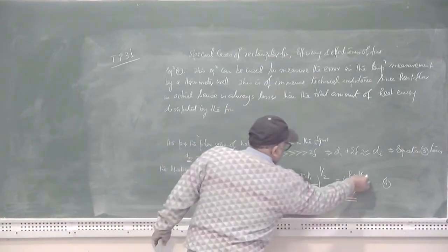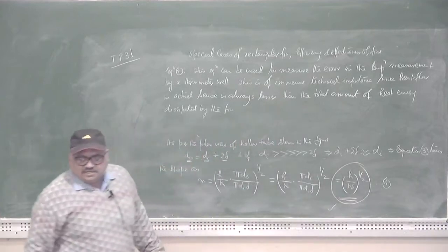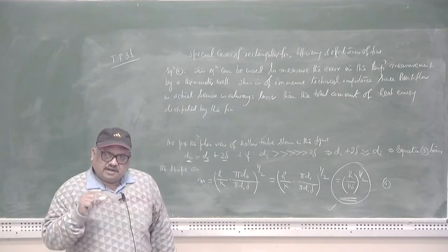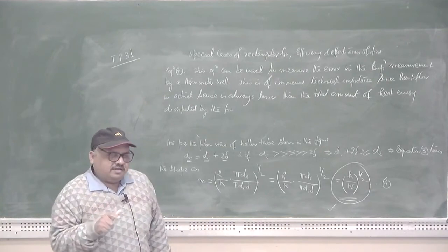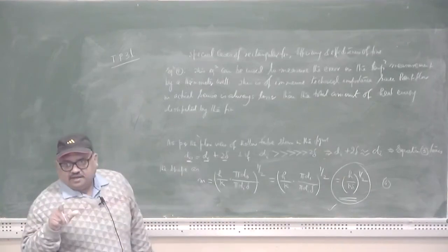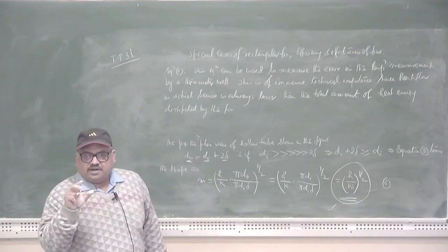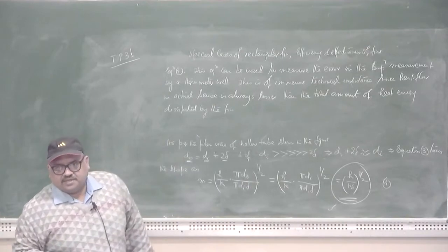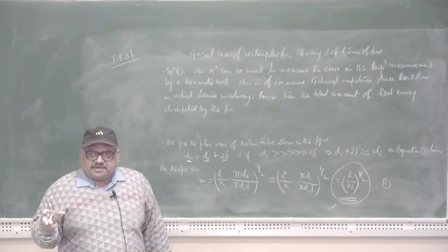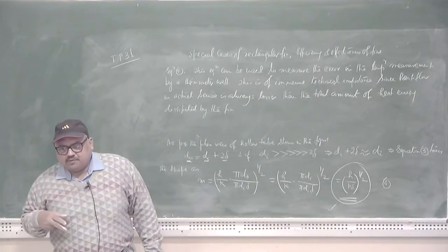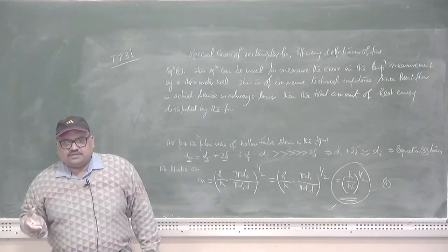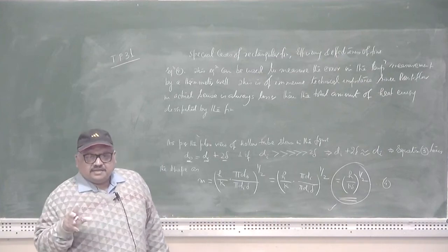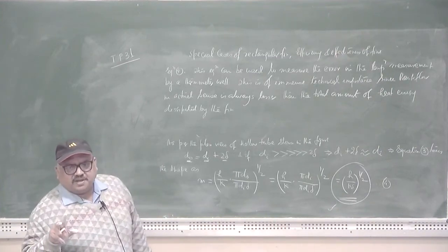So, by utilizing this equation, you can easily measure the errors in the temperature measurement, and applying that correction factor, a reasonable level of convergence can be obtained in both the cases. That is, the heat dissipated in the actual sense and the heat dissipation calculated as per the fin equation become more or less equal.